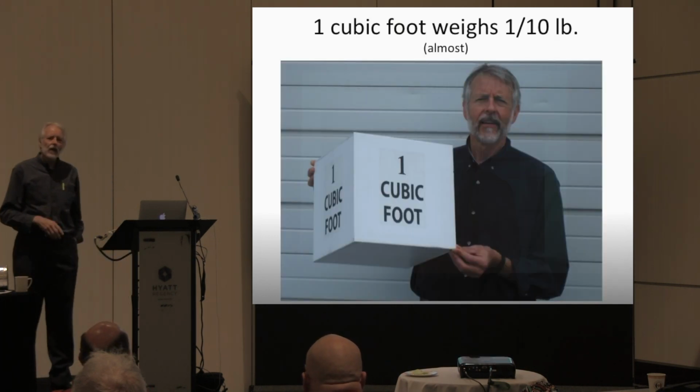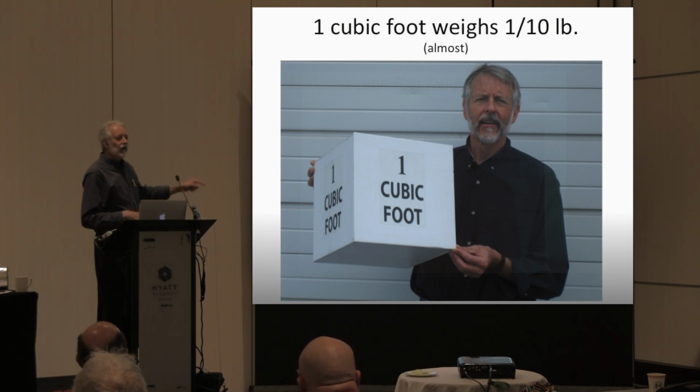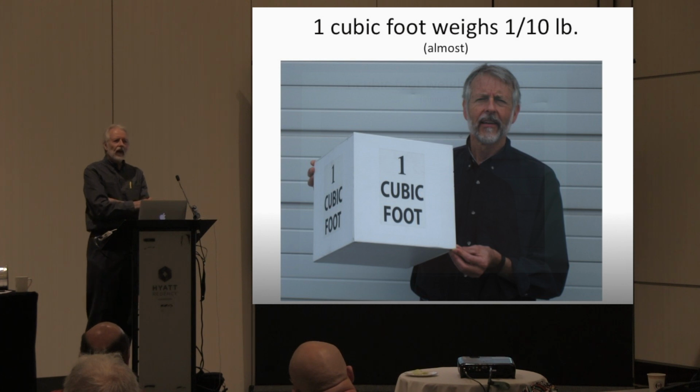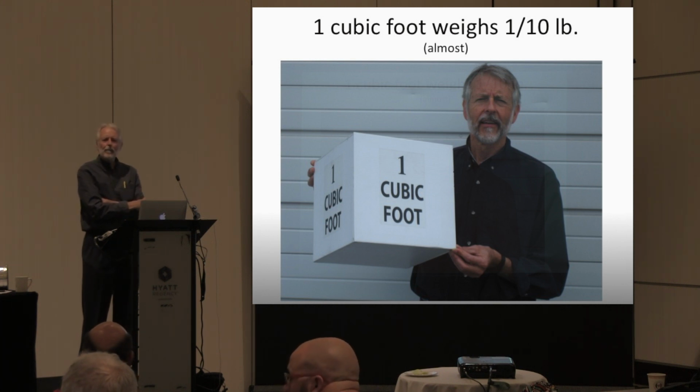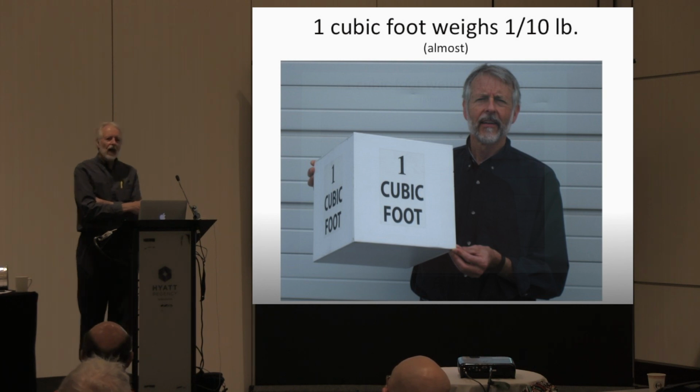We have to understand, before we go one inch further, what is air? That thing there is a cubic foot. It has weight. It has viscosity. It has momentum. It has all the properties of air. It's just a lot lighter, and we think it doesn't weigh anything, which is completely wrong. Our heating systems today are having to move between 50 pounds and 200 pounds per minute to do the job. If you were doing that with a shovel and a wheelbarrow, you'd be exhausted in 2 minutes.